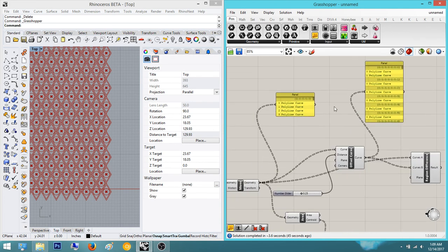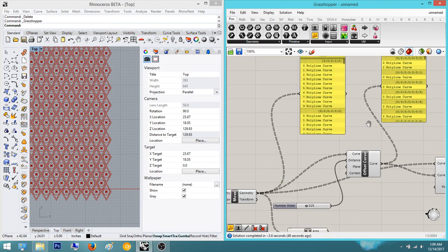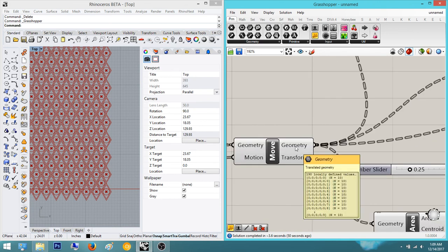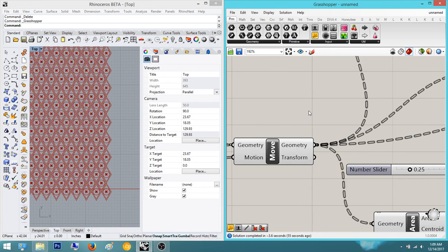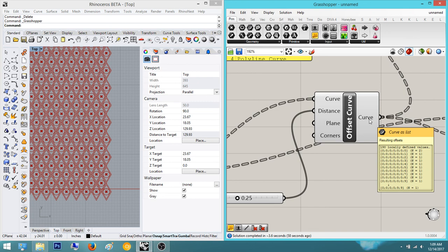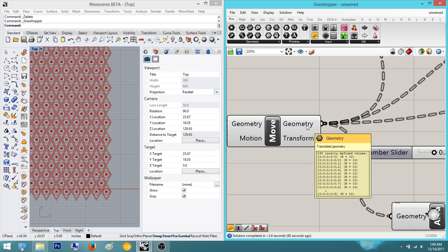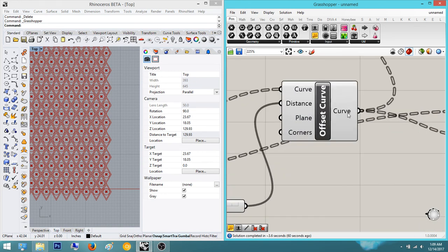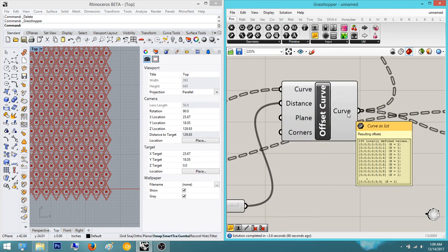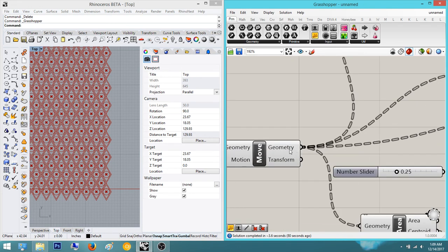And we can see that, the way I do it is if you hover over these geometry, you can see how many is defined. So we have 190 locally defined values right now, and this now has also 190. So it's not like I'm adding more lines, right? If it was saying 190 locally defined values and let's say 230 locally defined values, then it would have to create more surfaces in order to fulfill the script of it having 230 locally defined. But since they both match 190, we're good.